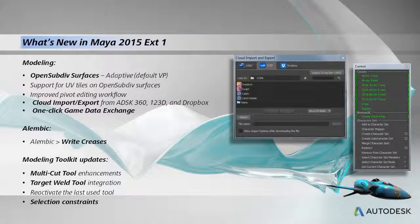So modeling toolkit updates, we're going to really spend a lot of time in the modeling toolkit here, looking at the multi-cut tool enhancements, the target weld tool, which is the combination of several tools for merging components. We've combined that into one tool. Things like in the modeling toolkit, the ability to reactivate the last used tool. So while you're working, you can just quickly reactivate and switch back and forth between tools. As well, we've added the ability to utilize selection constraints based off of different surface features on a model.